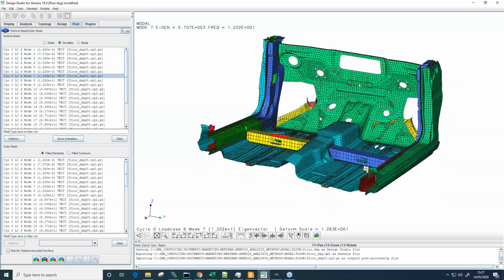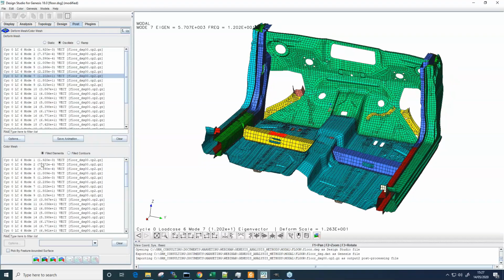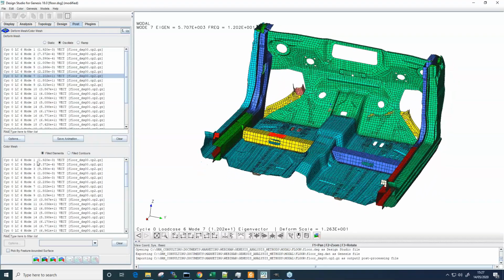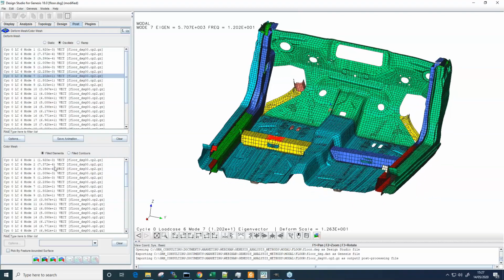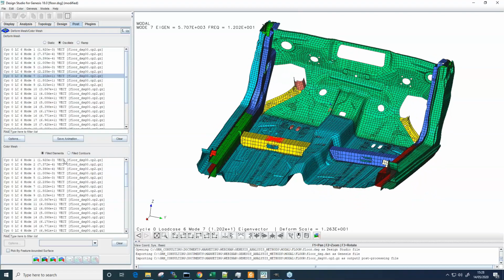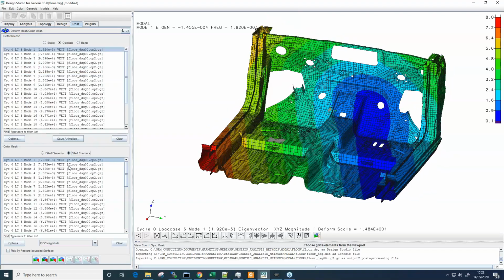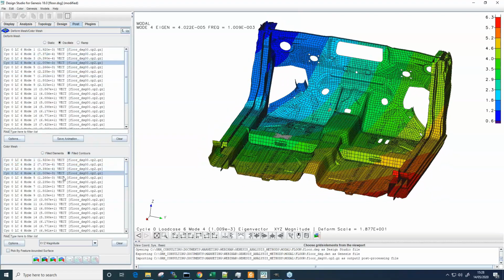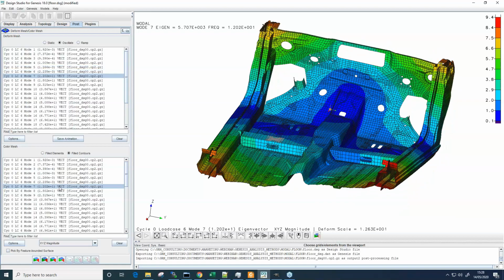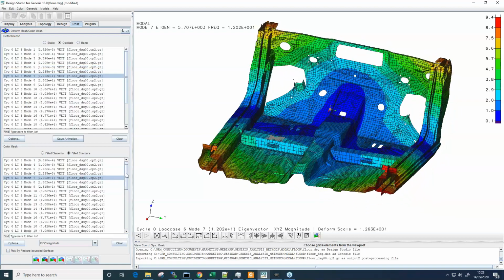And so here I've got my first mode. What you do see in the output list here in the lower section where our contour results are plotted is my mode shapes. These are called the vectors, so that's the displaced contour. They exist for the first 6, and then you get your displacements for the 7th mode.